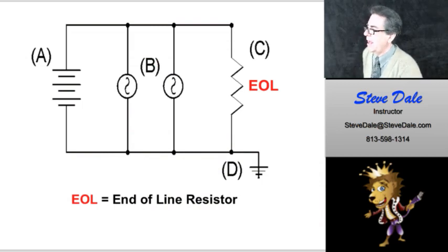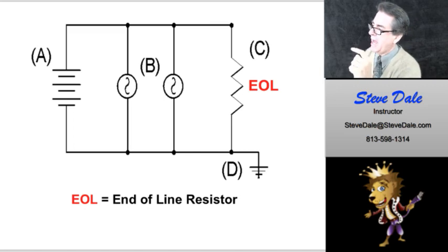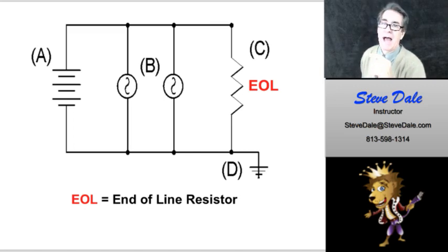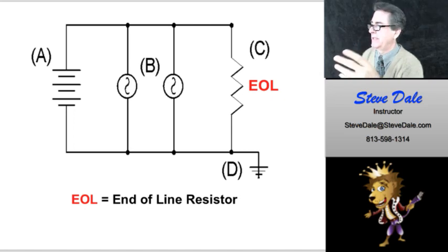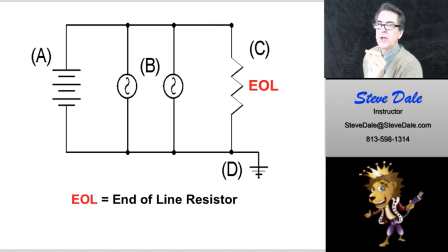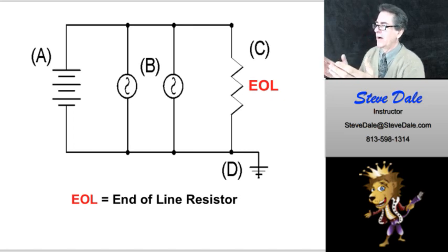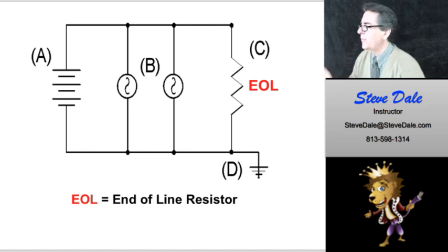So this is a schematic representation of a fire alarm system, smoke detectors. You have your power source being A there. That is a typical example of a schematic for a power supply. Now that could be a battery. It could be a DC power supply of some sort. It's a DC power supply. The reason I know that is because it's got smaller lines in between there. But in any case, regardless of that, you need to know that symbol. That symbol is a power supply symbol or battery, whatever, that's another synonym there. That could represent a battery or it could represent a power supply.